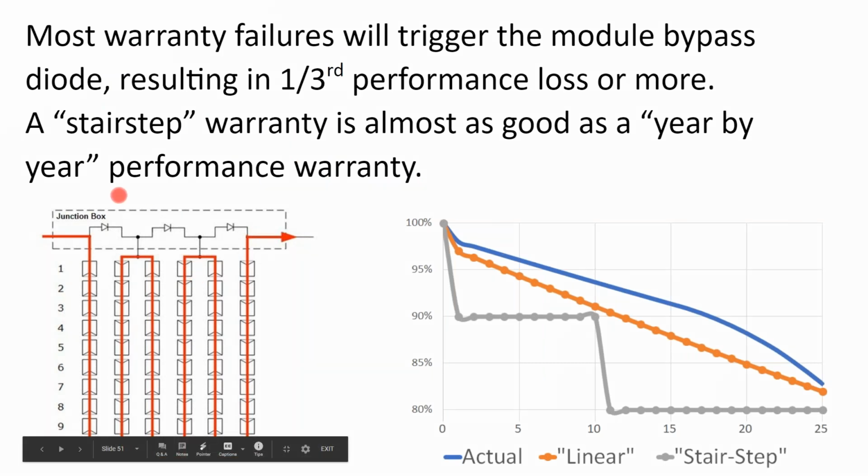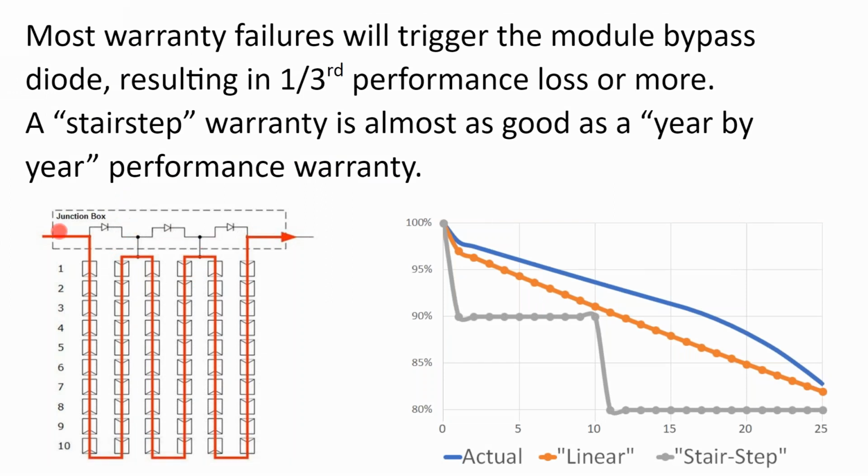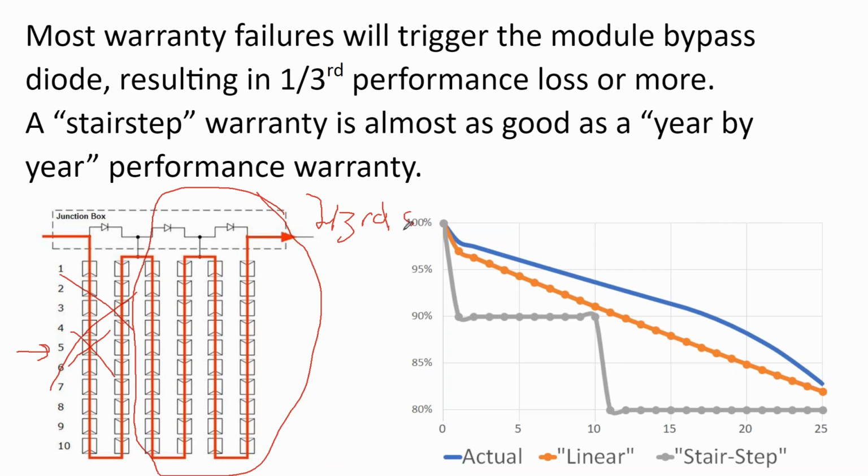Solar panels have bypass diodes built into them. And so if something were to go wrong right out of the box with a panel, and this is where, on the flip side, I've seen module manufacturer warranties cover things that may or may not have been their fault. So if one cell goes bad on a module in the first year or two, that could have easily been a solar installer putting an elbow or a knee on a solar panel and it not causing a break of the glass, but more of an imperceptible micro crack that puts more resistance into a cell. And what happens in that case is it takes the bypass circuit out, and all of a sudden the solar panel is producing about 2/3 if there's 3 bypass diodes, or 20% less if there's 5 of them, or 25% less if there's 4 of them.